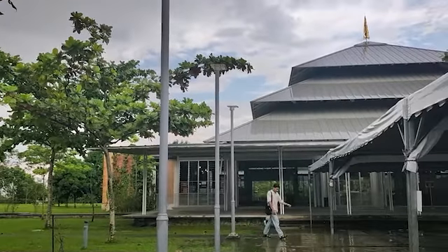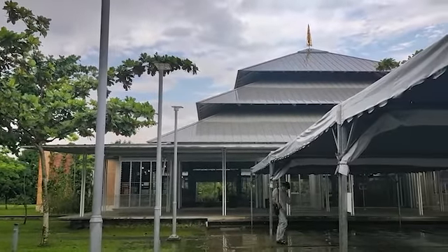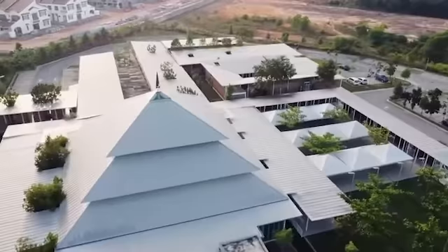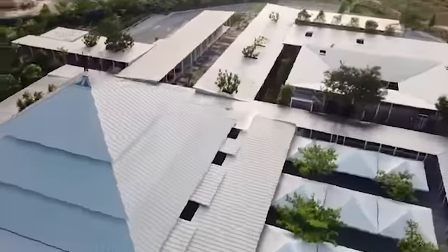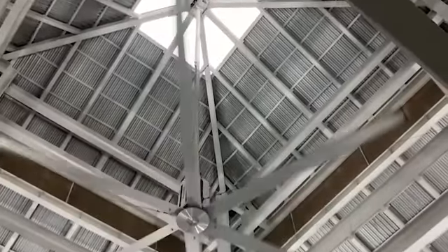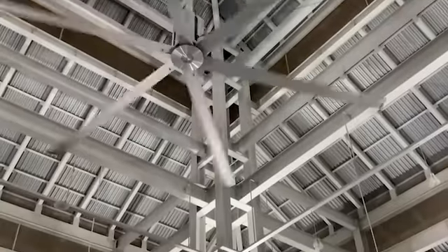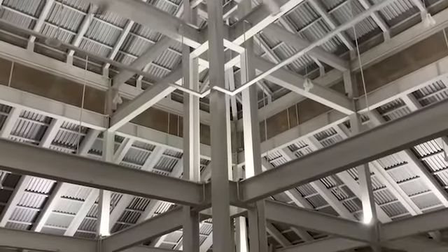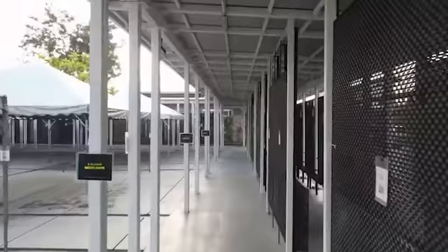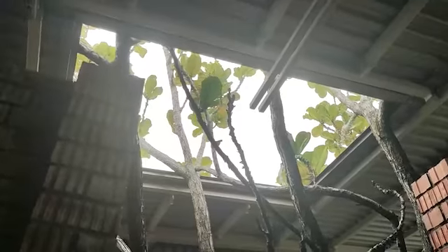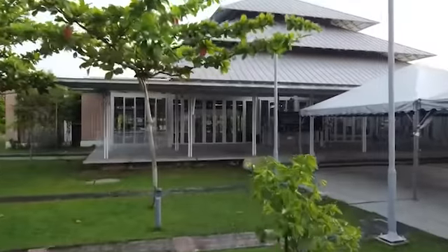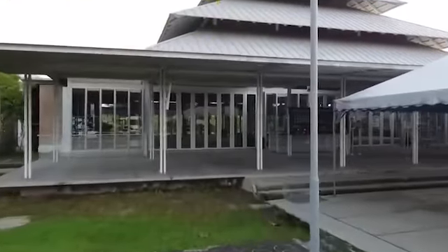The roof of Masjid Cyberjaya 10 is a modern structure that uses a 3-tiered roof design with the roof slope at a 30-degree angle at the main prayer hall, which uses structural steel roof framing and finish with metal deck roofing. Subsequently, the Serambi, spillover area, open court and corridor are constructed in a straightforward corridor layout, including a sloping roof for protection.